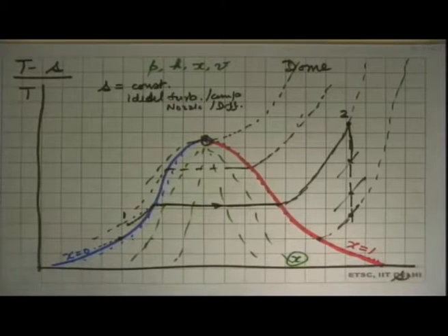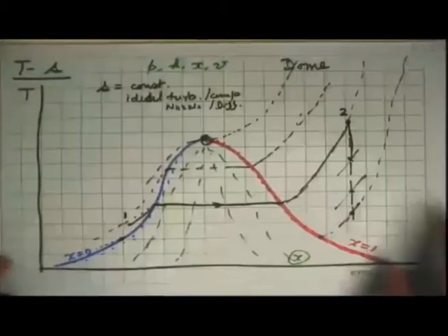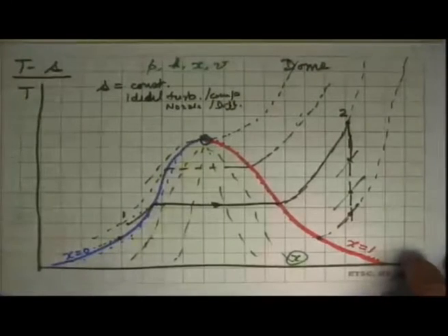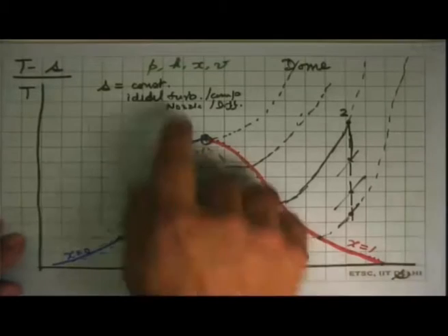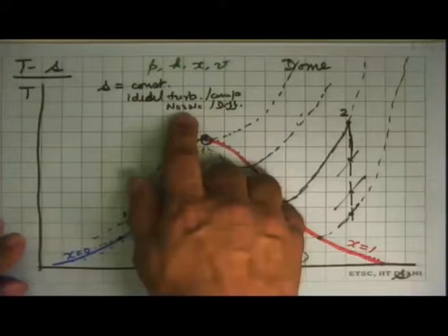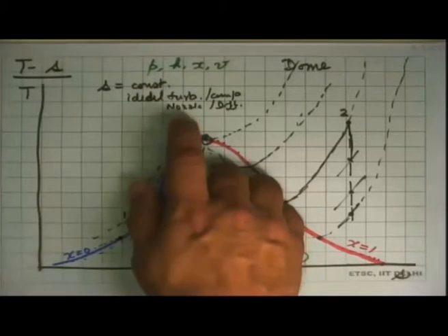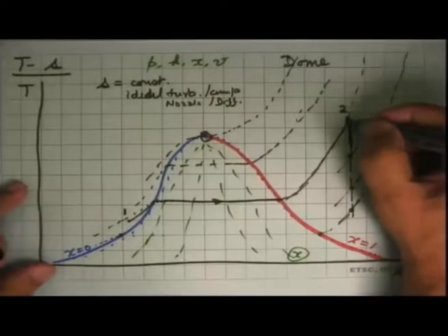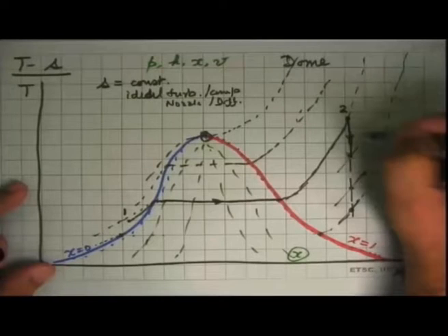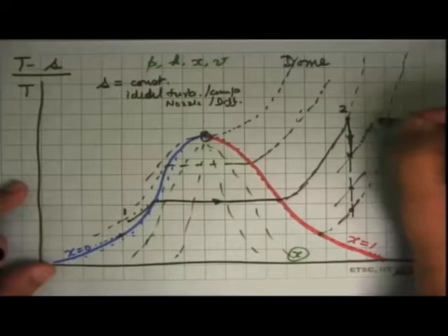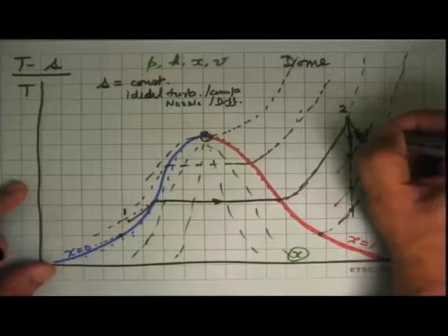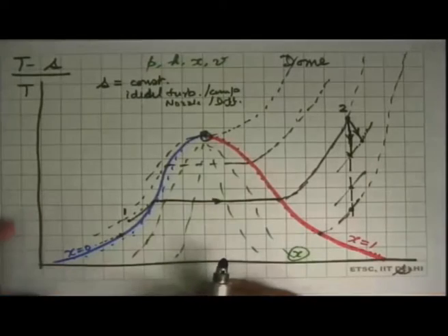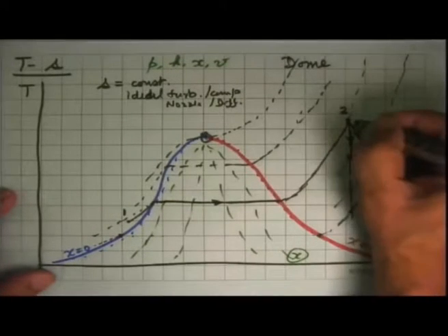And this diagram tells us that if any of these devices were non-ideal, that's what we learned in the laws, then there will be an increase in entropy, which means that while the ideal turbine will have come like this, the real turbine or the real nozzle will go like that to that point. And that will not be a solid line, so this has to be a dotted line.